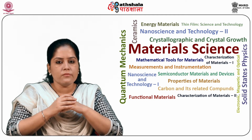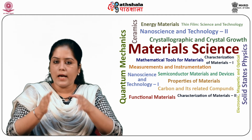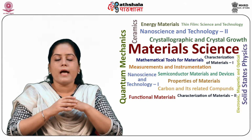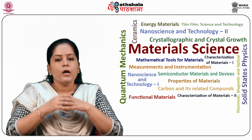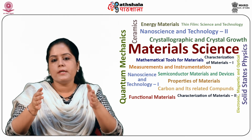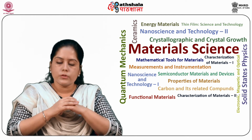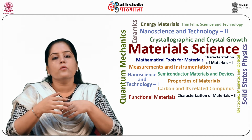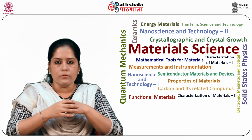Shockley in 1954 had introduced this general idea, not yet involving the impact avalanching to produce the phase shift. A number of different P plus N junction type structures are used today. So during operation, the diode is undergoing controlled reverse breakdown.